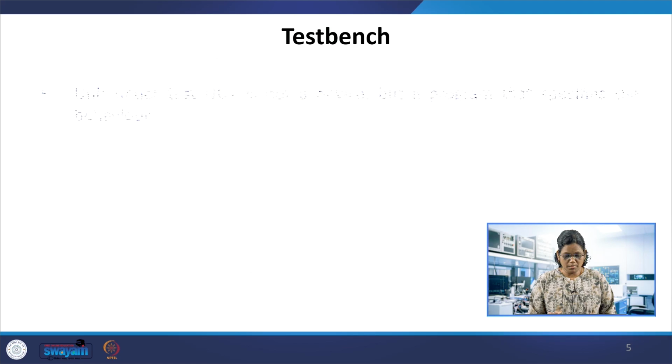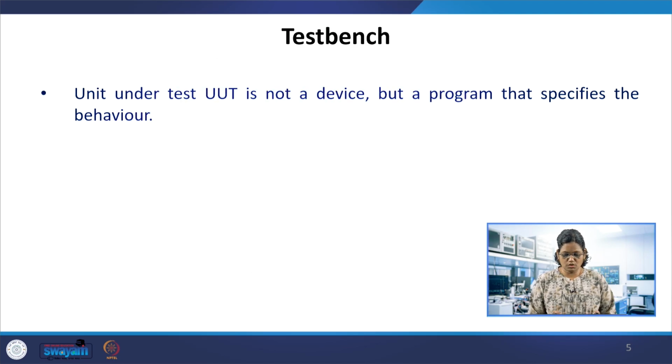So, coming to the test bench. The test bench is again a Verilog program, a .v file, in this case a Verilog module as we did in the previous examples also. It's a program which specifies its behavior, and it is used to test the unit under test. That means the unit under test is not a device here, it's a Verilog module, a design. The digital circuit described in HDL is tested using the test bench with various inputs, and outputs are observed.